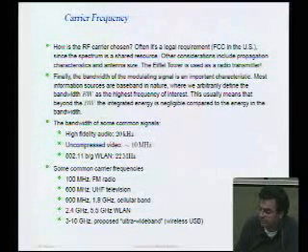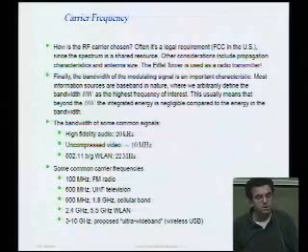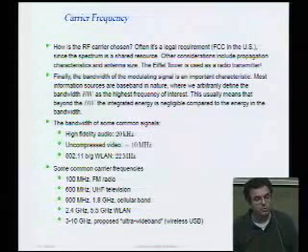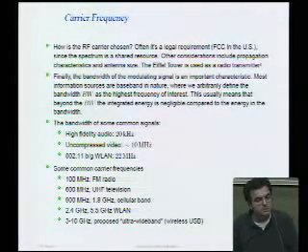An example of a spectrum that people would really like to go after is this UHF spectrum. And the reason is that UHF is probably one of the sweet spots in the spectrum, in the sense that you can get very good long-range transmission with reasonable antenna sizes. It's very good at bending corners and going through trees and walls and whatnot. And the frequency is still low enough that you can build very low power circuits. So it's almost like an optimal frequency for building, let's say, wireless internet.